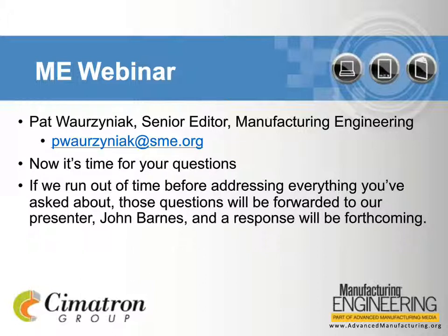Okay, John, we have time for about one more question. What else is new in Cimatron E12 for NC? Well, one thing I'm really excited about is our new stock model. In version 11, we had two stock models. One was for faster calculation, and one was for higher accuracy. We have a lot of customers that use Cimatron for micromilling, and they needed a really super precise stock model. And we have companies that create big bumper fascia molds, and they don't need such an accurate stock model.